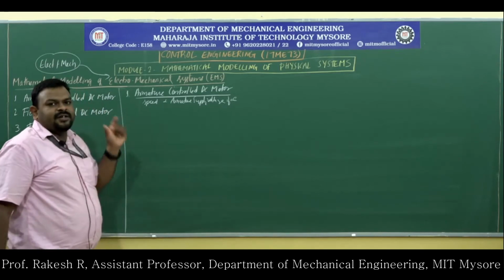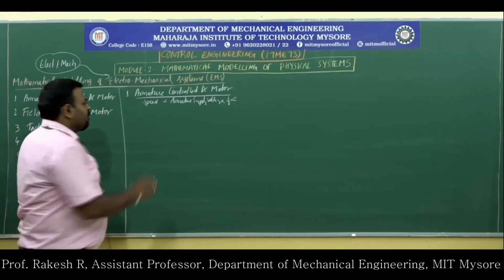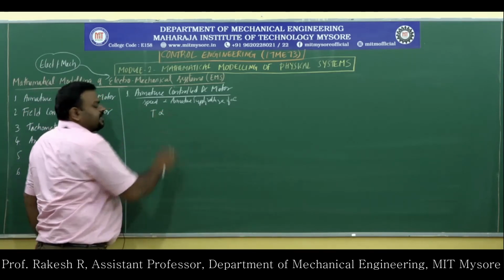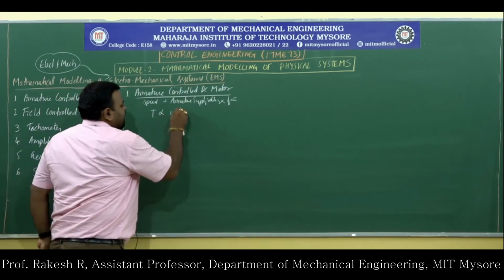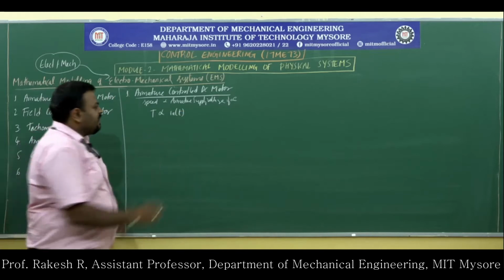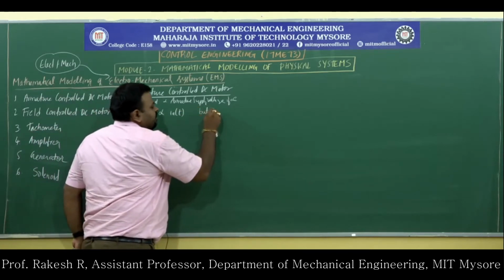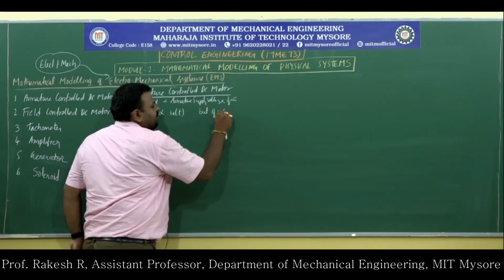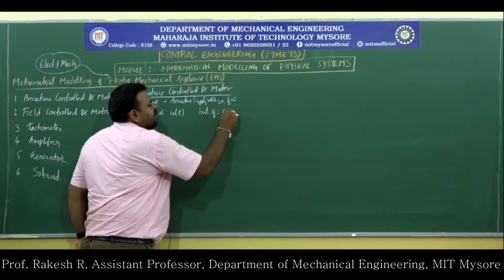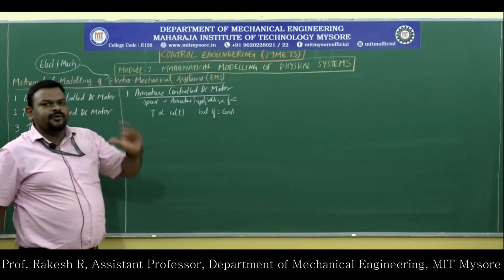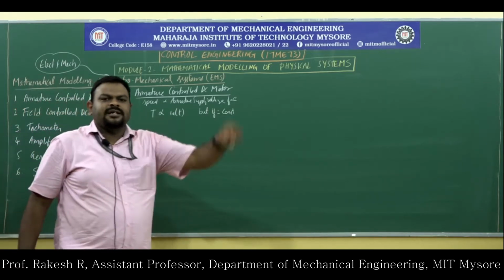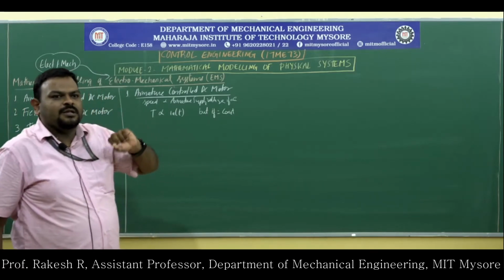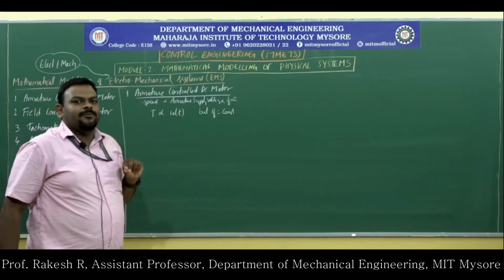Here, the torque generated by the motor is directly proportional to the armature supply voltage. So here we write Ia(t), but If(t) is constant. The field supply voltage remains constant. When you want to energize a motor in order to get rotation, there are two things: you can excite the armature supply voltage, or you can excite the field supply voltage.